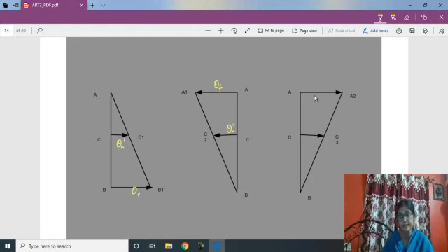And in the next level A will move to A2, and this is due to integral effect, so this may be considered as theta capital I. This is theta small I for input signal change, and again this is the flapper movement towards nozzle direction. This is say theta n 3 dash.